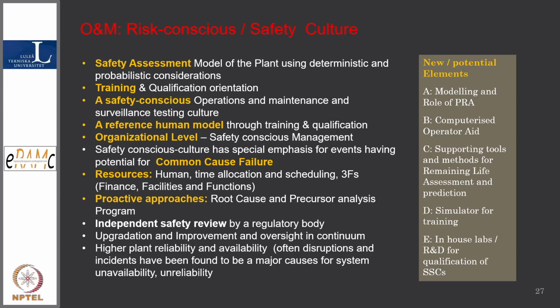If any event, there is a 1 in 100 chance of common cause failure, but if it happens, an in-depth analysis of the common cause failures has to be done, and the causes, even though the plant has many provisions to avoid the common cause failure. I said physical separation, independent power supply, and then elevation, location of the component.